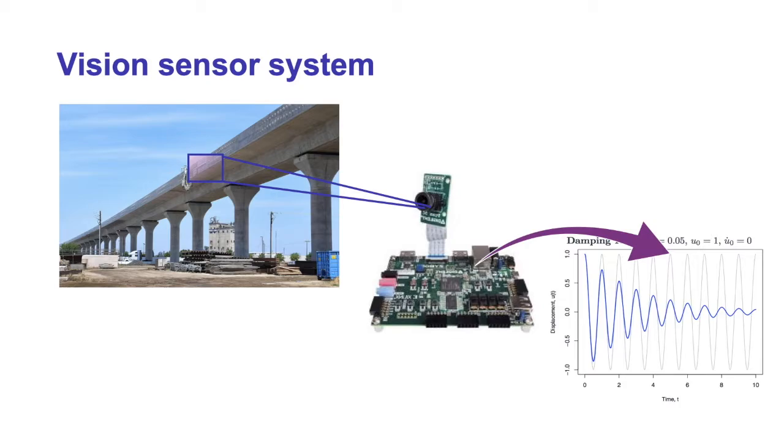Here we can see a depiction of the concept of using computer vision for measuring structural displacements. First, the camera is fixed in a given point and takes a video of the structure or the part of the structure of interest. The computing unit acquires and processes the video images to extract displacements either in real time or after post-processing. It is worth noting that the images can always be post-processed to alter the measurement point, a useful feature that is not available in other structural sensing systems.